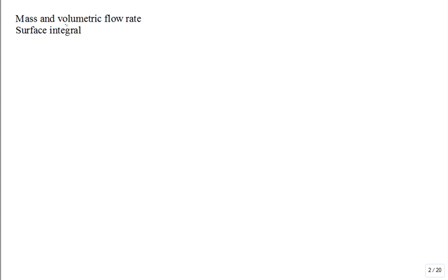There's something called a volumetric flow rate. Let's say I have my control volume here, and right in here is a patch of area. I can define the outward directed normal, and so I can write either dA, that's common, or I can write n dA. If you say dA, you're indicating that that's a vector entity. It has direction and magnitude. The direction is outward directed, and its magnitude is proportional to how much area you're talking about. Here they separate the direction from the magnitude.